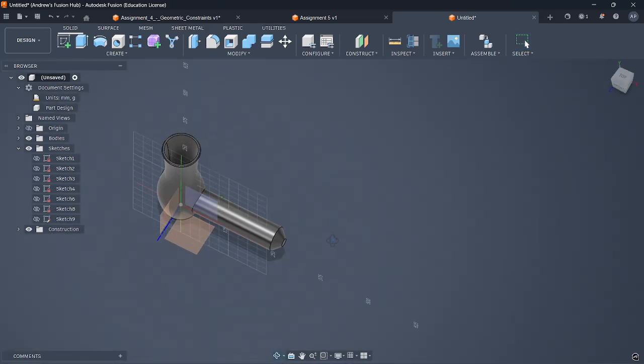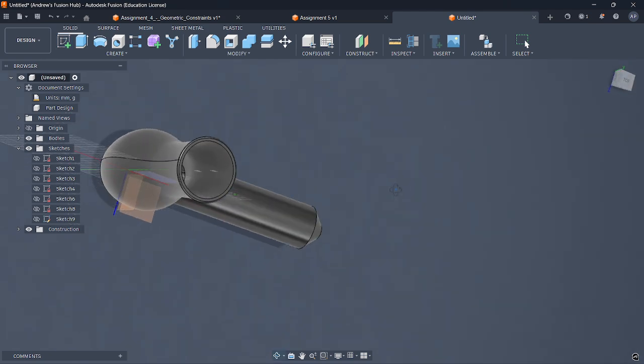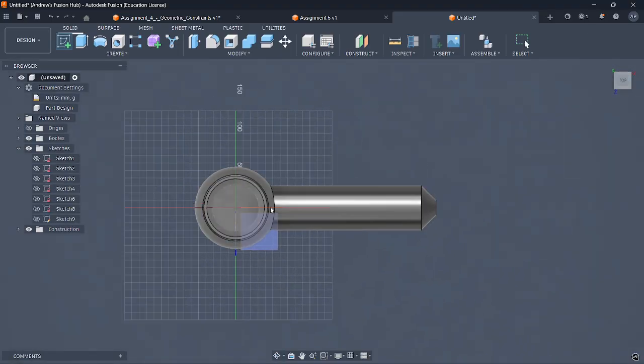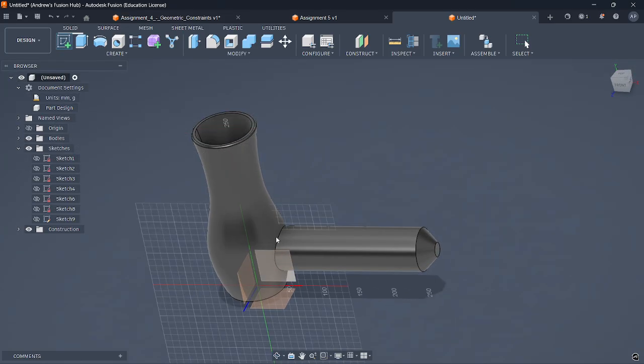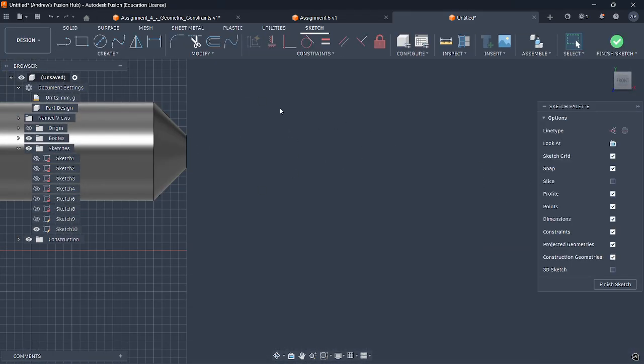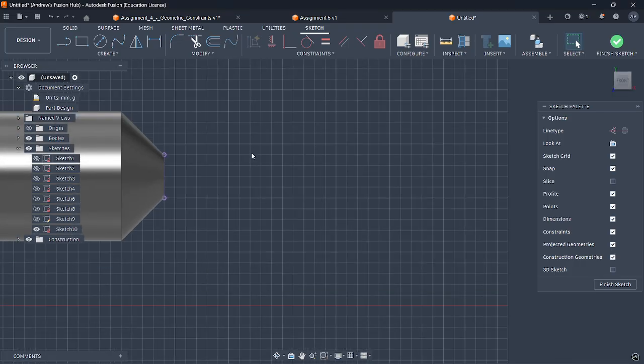So I made a sketch on this plane. Again, if you look on it from the top, the plane is here, right? So it cuts through the center of the hairdryer. So I'm going to use that. I want it to go off this face. So I'm going to reference it with a projection by pressing P, selecting that line, pressing OK. You can see here it kind of snaps to the midpoint with that triangular icon.